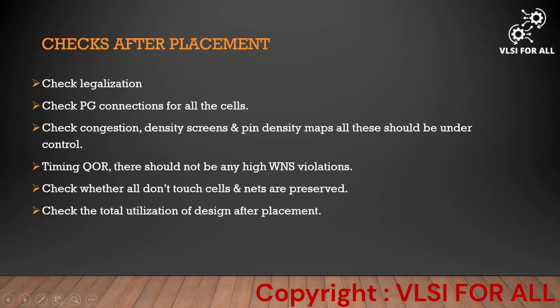Moving to the next stage, checks after placement. Once placement is done, we need to check a few things. The first one is legalization. Check legality will be the command. With that command, we'll see whether any legality issues are there. In some cases, some cells will be overlapped, and some cells are not aligned properly to the site rows. Likewise, it will be reported in the legalization.